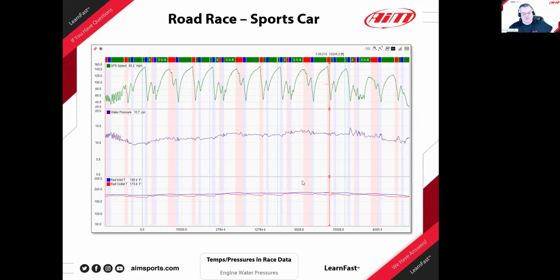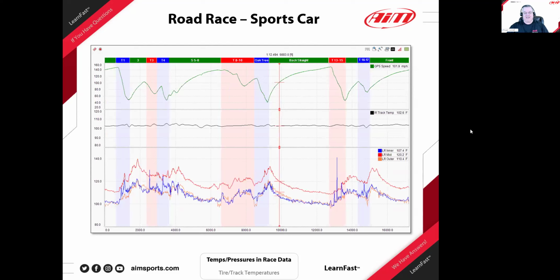And if the car was running up at 212, 220, you would want a bigger delta, and you want your radiator to be a little bit more effective at that point. So possibly qualifying tape, you might be right, Matt. But just understanding and knowing it, having a temperature sensor on both sides and a pressure, is very, very valuable information for you in your design and your maintenance of your car, let alone as a driver in the car at the time. So very, very cool information.